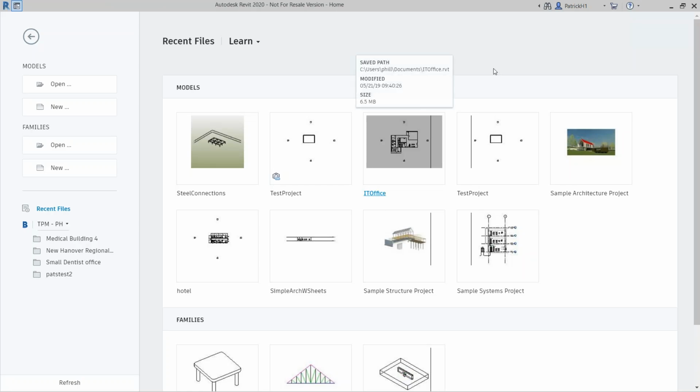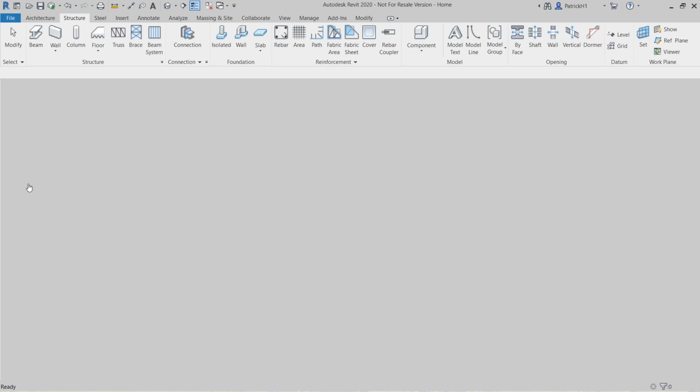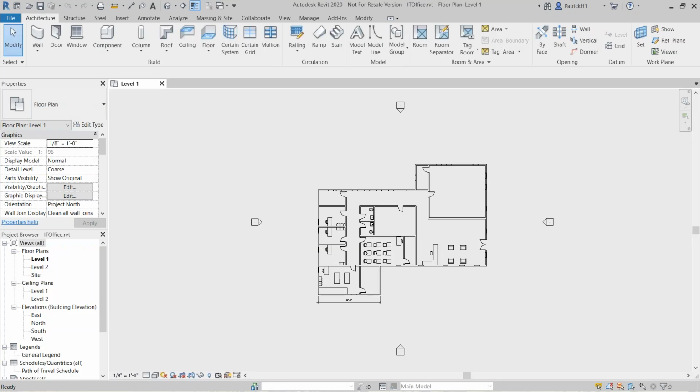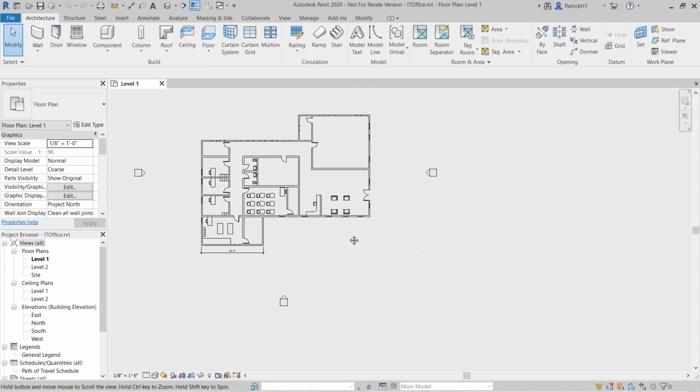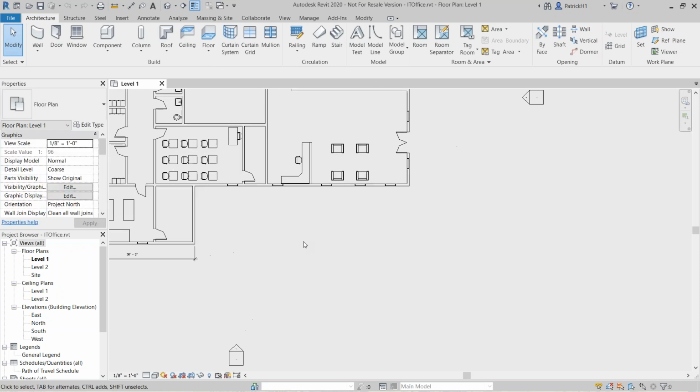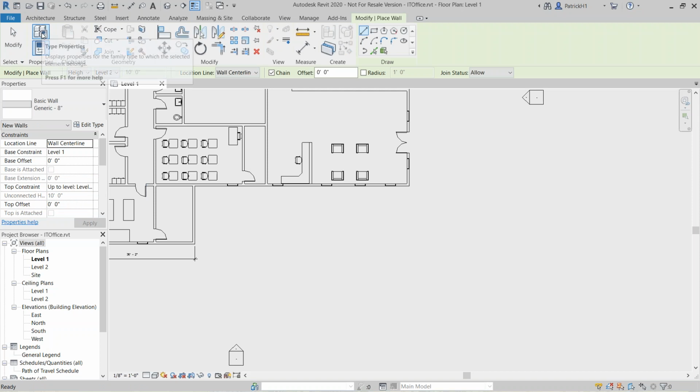Let's go back, and we're going to switch over now to some more generic geometry here. We're going to open up an architectural base file. And opening up this architectural file, a few things to look at. One is, let's just go ahead and come down here to the bottom area, and we're going to see how easy it is to simply draw some elliptical walls. It's pretty straightforward. Under our wall command, you'll see we now have added the elliptical wall command.